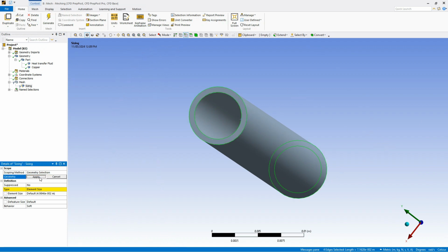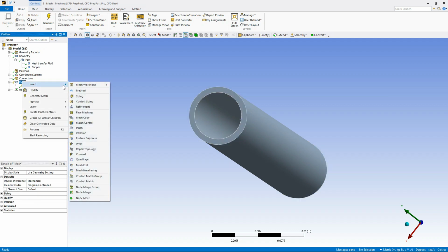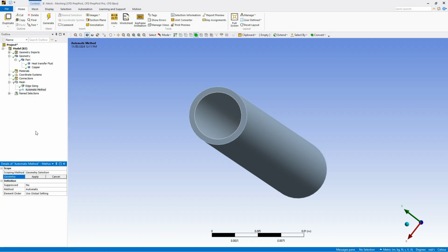Then click on geometry, just click on apply. For this we're using the number of divisions. Then for the number of divisions that will be 45. So we use 45. So that's the first one. Go back to the mesh, right click on it. Then we are going to select the fluid body. So as you can see, we select body tool that is there.